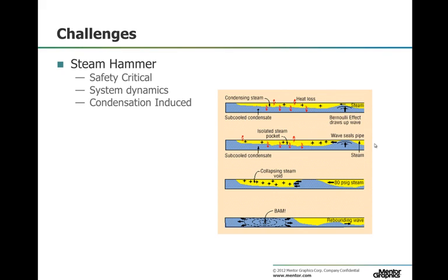This is similar to water hammer, but the consequences of steam hammer can be much more severe than in liquid systems. The level of stored energy, both in the temperature and pressure, makes system failures potentially catastrophic. In liquid systems, pressure waves are typically generated through some sort of dynamic action in the system, such as a rapid valve closure. While this can also occur in steam systems, the less predictable and potentially more dangerous cause is uncontrolled condensation.